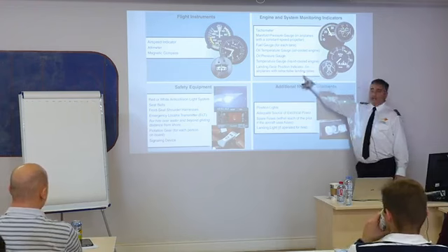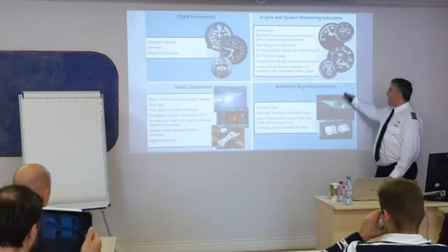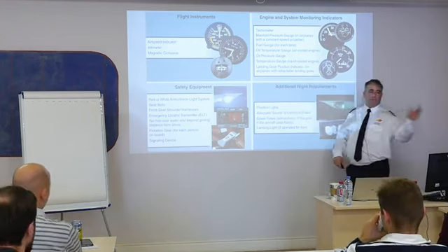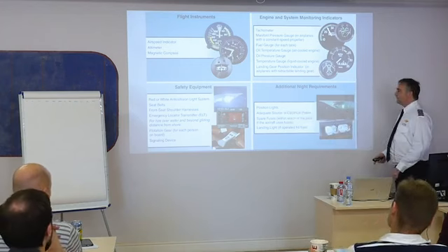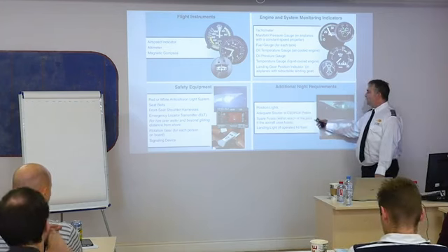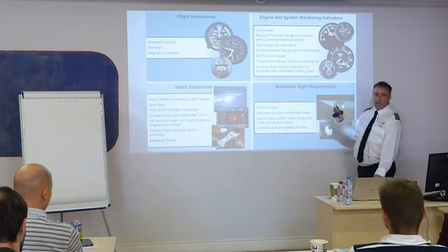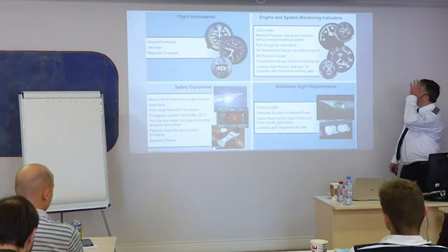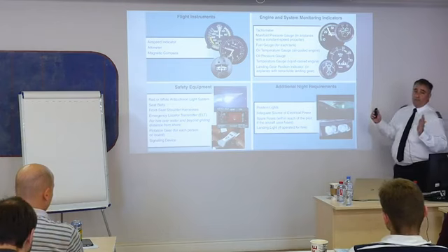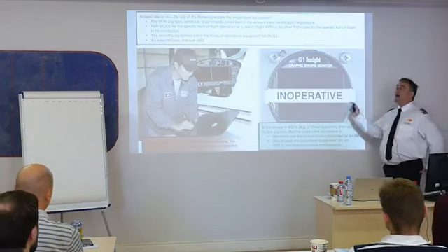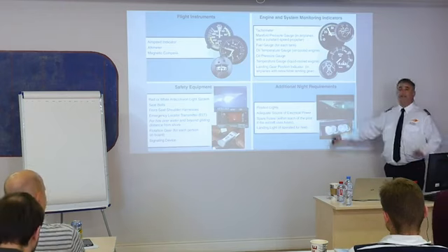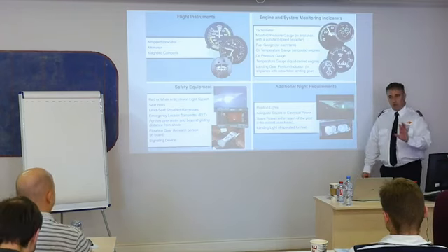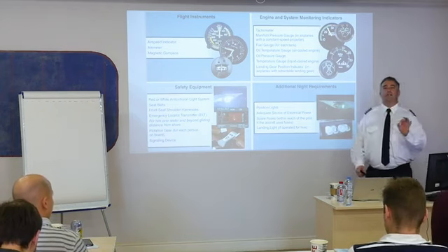Landing gear if I have a retractable gear. Night requirements, I need position lights, which is that red, green, and white light. Adequate source of power, spare fuses or circuit breakers, and a landing light if operated for hire. Now, some of the stuff in the airplane might not work. As long as it's not any of this, that's okay. Nothing wrong. I'm saying some of the stuff might not work.